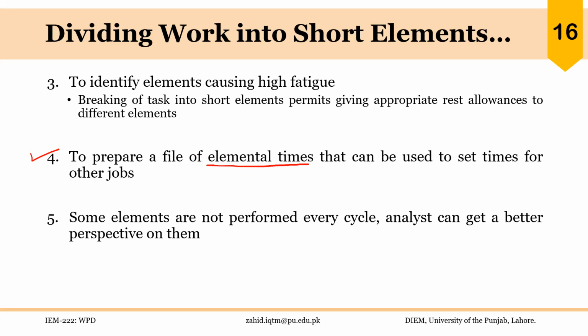So you only need to time the new elements. So that is a very important application. And if this is done universally as has been done, then these elemental times can be used in different organizations. So such databases of elemental times that can be used universally are called PMTS.